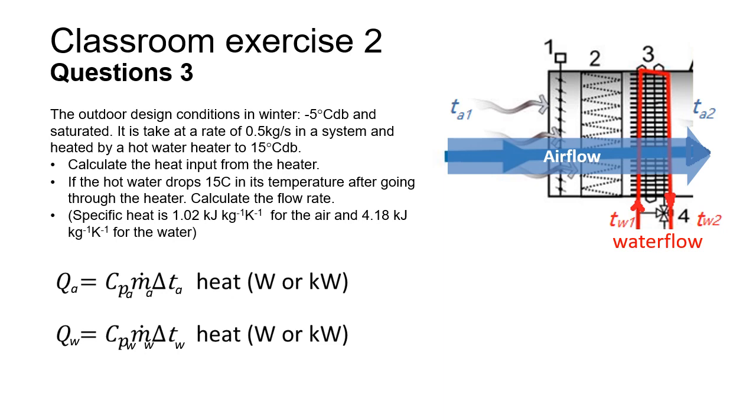So now right here, the specific heat of air is 1.02 kilojoule per kilogram per K, multiplied by the mass flow rate of 0.5 kilogram per second, and the temperature change is 20 K. So there's a K here, kilojoule per kilogram per K. So K cancels, kilogram cancels. So it will be kilojoule per second.